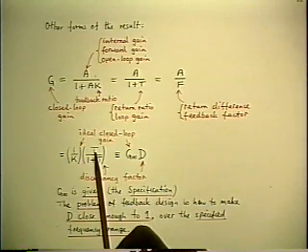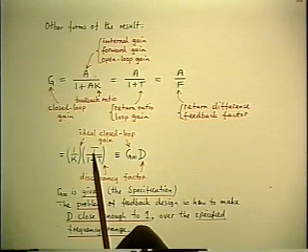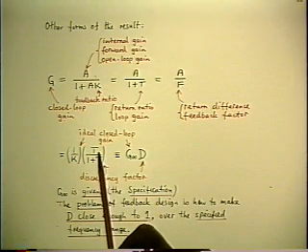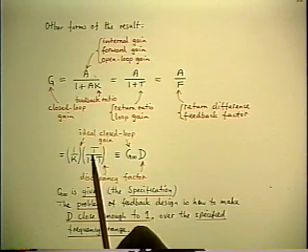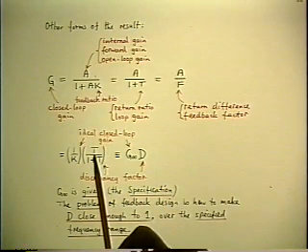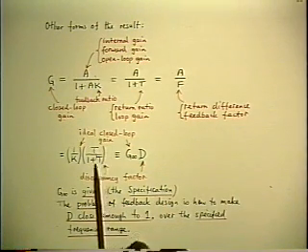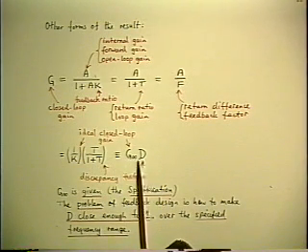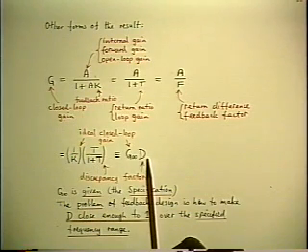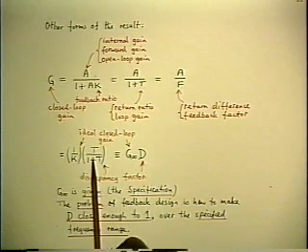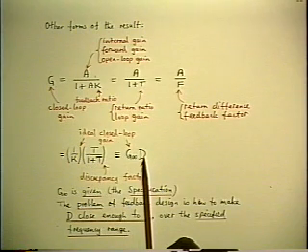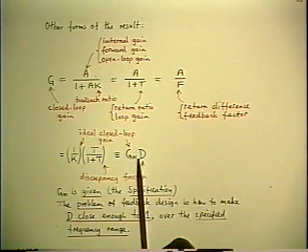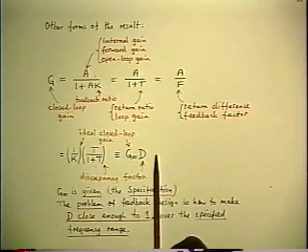Because t is going to go to 0 eventually at infinite frequency, regardless of what else you do. So no matter how big you make it at lower frequencies, ultimately t goes to 0, which means somewhere in between it crosses unity. And where t crosses unity is about where the d starts to fall off. See, if t is 10, d is 0.9. So it's still pretty close to 1. If t is 1, t over 1 plus t is already 0.5. And you're starting to deviate significantly from the ideal limit. And ultimately d goes to 0 as t does.